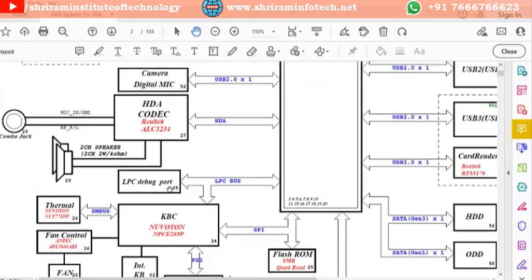And this one is again one more important component, called the SIO. In a circuit diagram SIO is not mentioned; normally a KBC or ENE is mentioned. KBC means keyboard controller. And this SIO's number is 285, it's a make of Nuvoton.